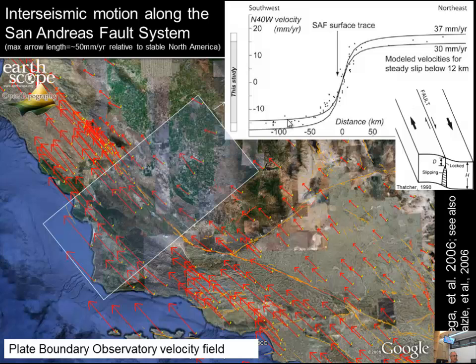So in the last case for the co-seismic in San Francisco, I knew the slip on the fault, which was like 4 meters total because it's 2.5 and 1.5. And so I was looking at D. But in this case, I said, well, I know D because of seismicity in the fault region. I know it's about 12 kilometers. But what I really want to do is figure out what the rate is, what the U dot in his equation, or just the deep slip rate is.